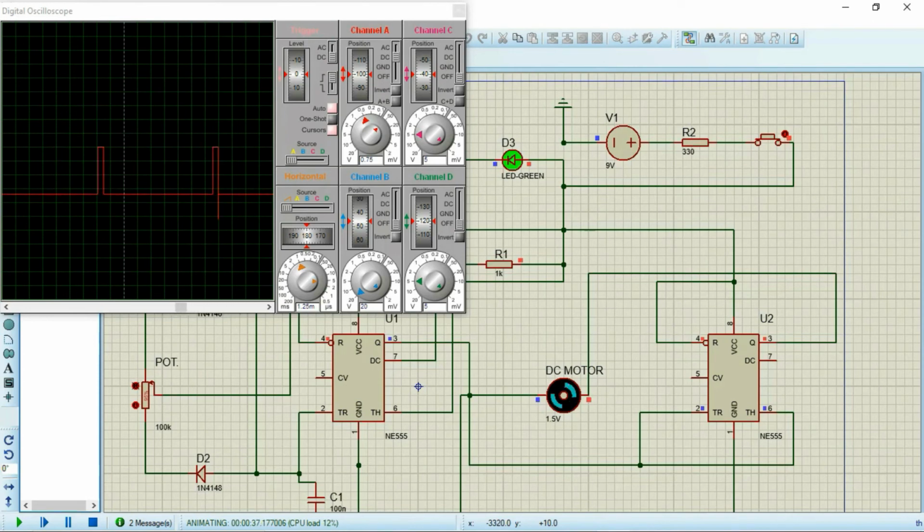Now we can see we set the maximum duty cycle of 100%. The motor speed increases. We lower down the duty cycle to 32%. The DC motor moves counterclockwise, which is reverse motoring in the third quadrant, where we have negative torque, negative speed, but the power dissipated is still a positive value.